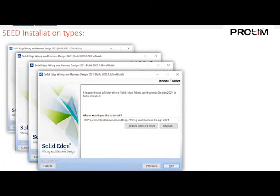So in the next step, you would locate the location for the installation of the application folders and image files that will be stored. Now it's important, there's the next page after this install folder where you put the application. The next folder basically goes in the same location, the C, Program Files, Siemens, Solid Edge Wire and Harness Design, but there's an /images folder. So any image that you want to use, say a company logo or maybe the image of a symbol or some sort of image, in order for Solid Edge Electrical Design to read that image and have access to it, it has to be specified in that images folder within the Solid Edge Wire and Harness Design application folder. So just a side note there.